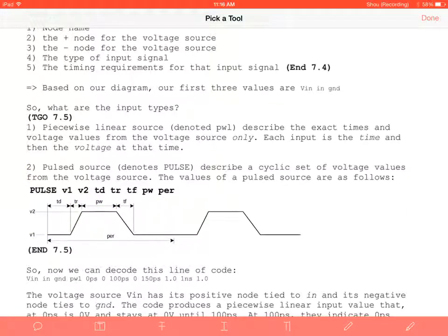What's going to happen is that the period will keep cycling. So let's say that your pulse width is 100 nanoseconds, and your initial delay is 10 nanoseconds. You would have a rise time and a fall time, and then you have this amount of time before your period starts again. You can think of it like recalling from algebra, when you're talking about shifting a function. You can think of this the same way. It's going to recycle, and the first 10 nanoseconds would be the first 10 nanoseconds of this, and so forth.